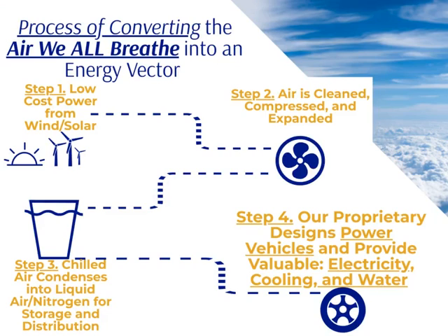Just a real quick introduction to the process. You have to start with the power source. The reason liquid air is considered a form of energy storage is because it requires energy to liquefy the air in the first place. And then most of that energy is recovered at a later point in time. So you start with the energy source. The air is then cleaned, compressed, and expanded. And that expansion is what allows the air to be chilled into a liquid.